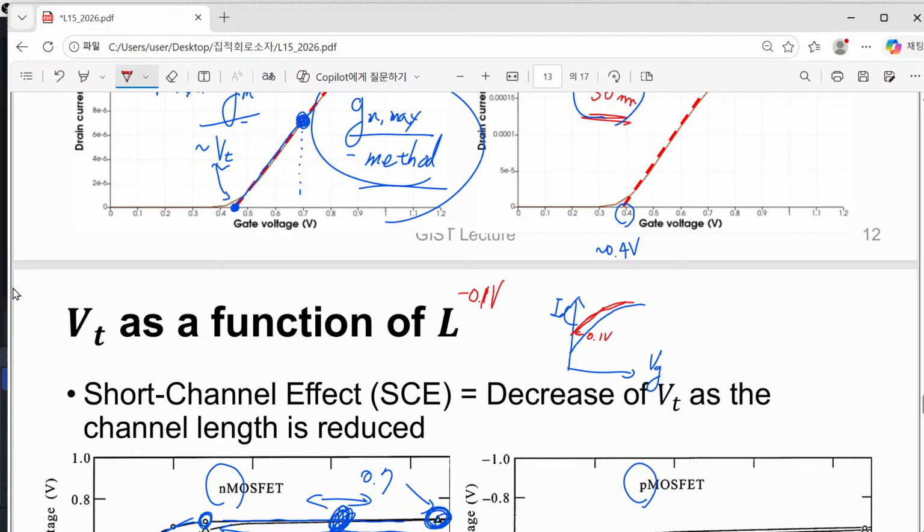And unfortunately, that means that when your gate voltage equal to 0, the current you have at this case, that is called as your off current, will show about more than 10 times, almost 100 times increase in your off current. Well, is it big deal or not? This is really a big deal, because that introduces so many problems in your circuit.